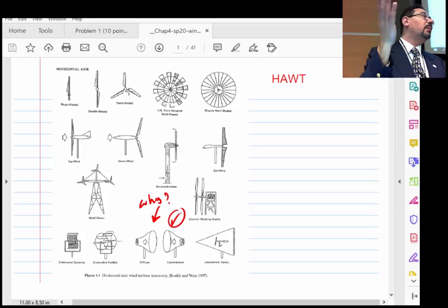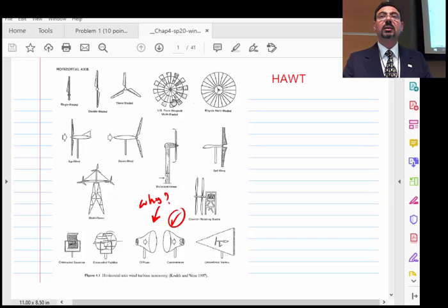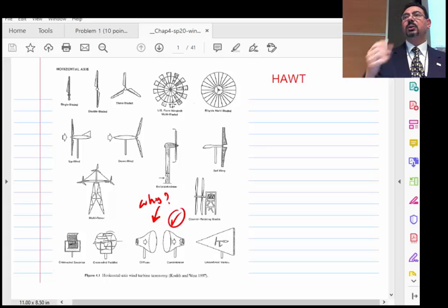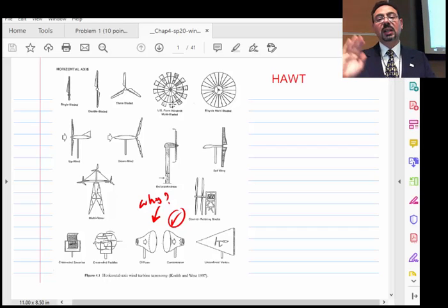The one that does this is the American farm wind turbine. You know, those are the ones that you can see spinning with the wind easily. Right? It would be like this guy. And even those have a mechanism so that they wouldn't spin immediately. They have like a tail, and the tail is spring loaded, and there's a little bit of mechanism so that it does not just jump up and down, you know, there's a little bit of damping action in it. But anyway, so the horizontal axis wind turbines basically always need to adjust their yaw angle, right?